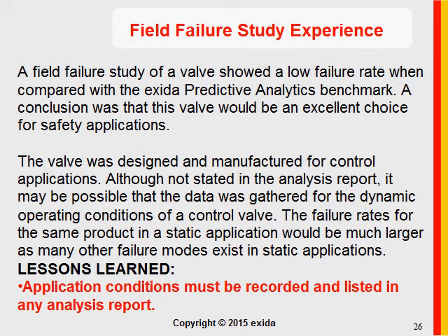Okay, field failure studies. We see that they exist, they can be valuable, but the outputs have to be checked for reasonability. The data collection process must be checked, and when that is done, then that data is what I call validated field failure data, and we use it to calibrate the FMEDA results in a nice closed-loop system.